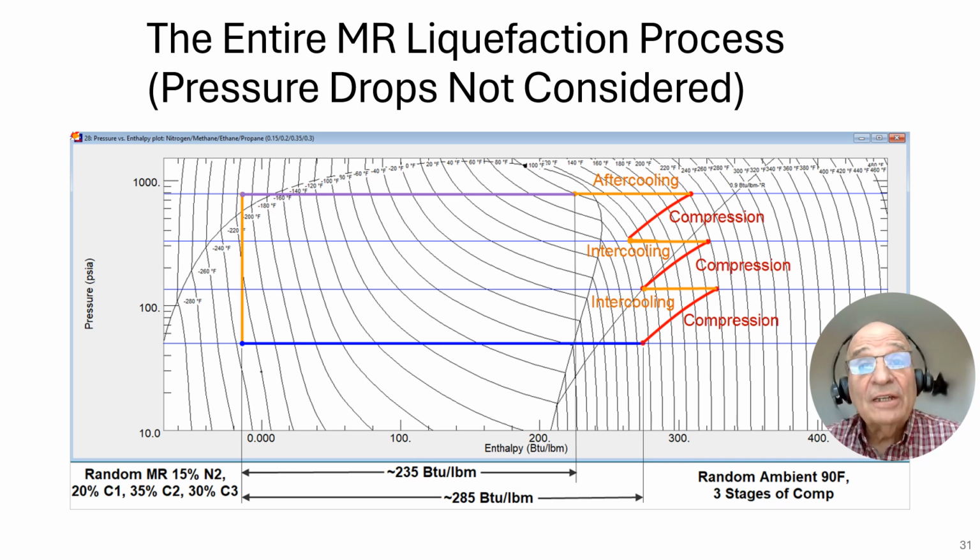That is actually done on some LNG facilities, but only in the very large ones like export terminals. They'll use a liquid expander here in order to extract work from the fluid, because don't forget you're at a high pressure here. And once you extract work, by the first law of thermodynamics, you're dropping the enthalpy, which means you're dropping the temperature. So it gives you more refrigeration and a byproduct of work, which you can use to either generate electricity or lessen your compression work that's needed here.